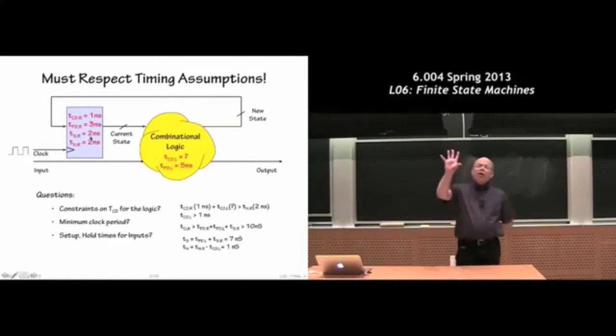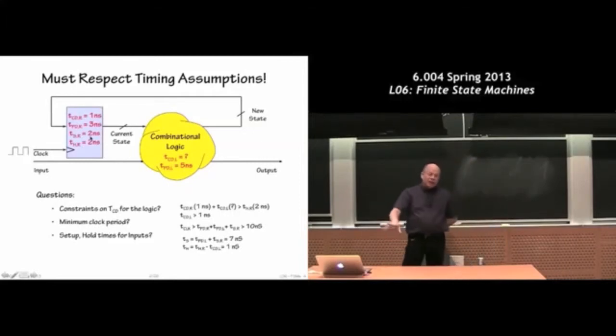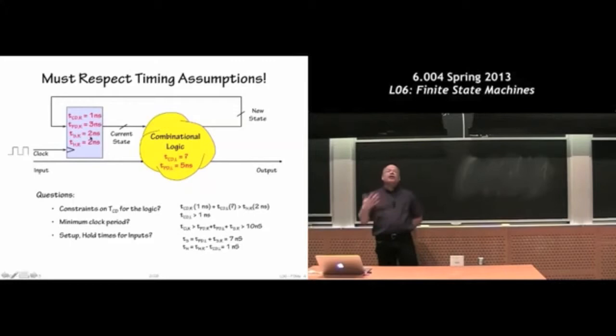And if any of you try overclocking at home, often what happens is when you're making your processor go faster and faster, making the clock faster and faster and faster, at some point you end up violating this particular timing constraint, and now the circuit is no longer performing correctly and your operating system crashes, and you say, well, maybe it's actually not a 5 gigahertz processor, and you turn your clock back down a little bit.